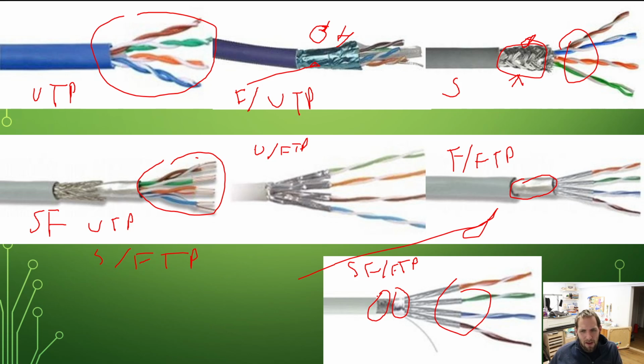And the other thing that you should be careful of is running Ethernet by power lines, because those, especially in an industrial environment, are going to be carrying a huge load for the most part. If you're running it not over the motor, but over the motor's wires, every time that motor turns on, there's a big surge of energy, lots of current flowing through that wire that's going to radiate electrical interference. So not just the equipment, but also the power lines is something you want to be aware of and keep in the back of your mind.